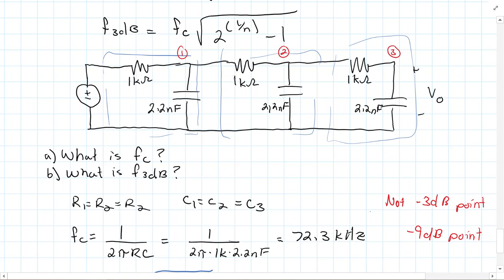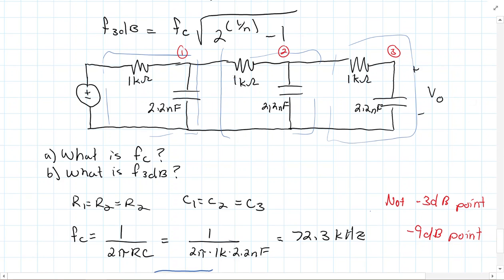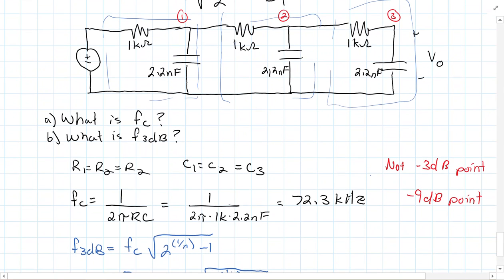That load is going to drop the equivalent resistance to 500 ohms. So just on that first stage, we're actually dropping that frequency because our REQ is not 1 kilo ohm, it's actually 500. And then we have to do the whole thing there again. So you might say, well, how could our equations be wrong here? Well, it's having to do with a loading effect that we didn't account for.